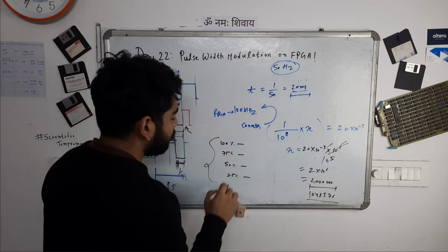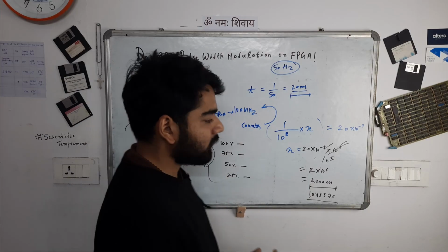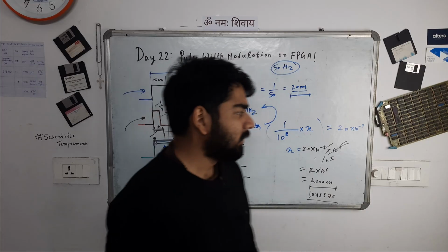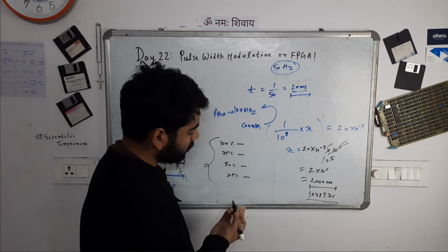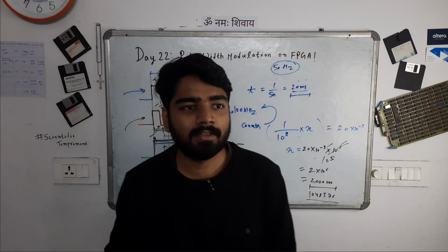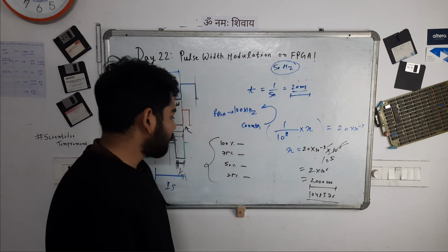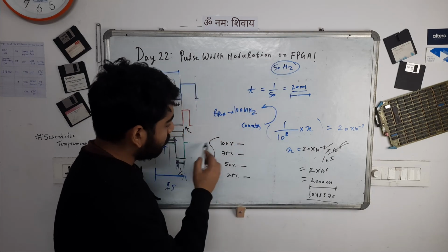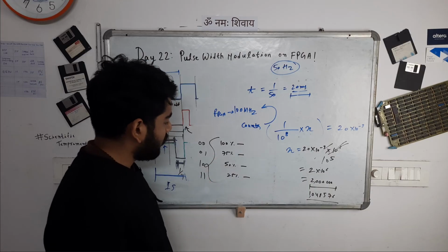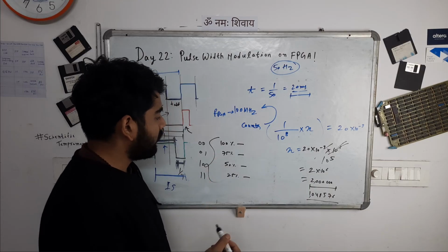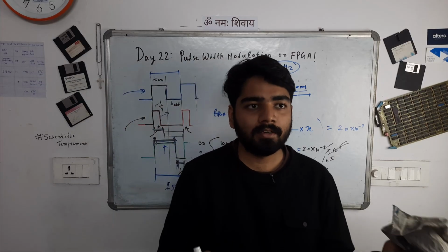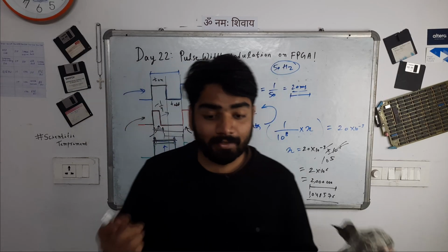Let's have these four duty cycles programmed in our FPGA. And how do we select the duty cycle? Let's select it using switches. Since on our Nexys FPGA board we have lots of switches, we'll use 2 of them, because using 2 of them I'll be able to map it on the switches, and therefore we'll have lots of different PWM signals to compare in a single design.